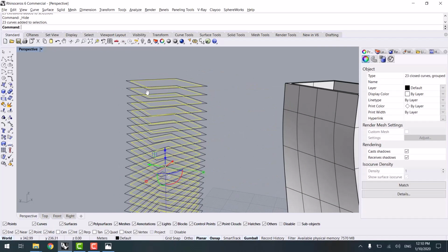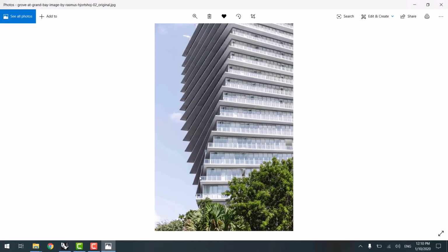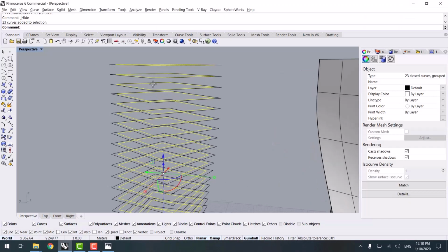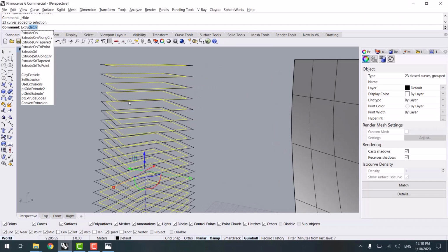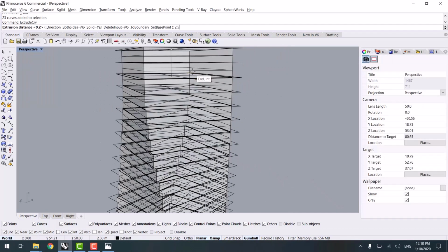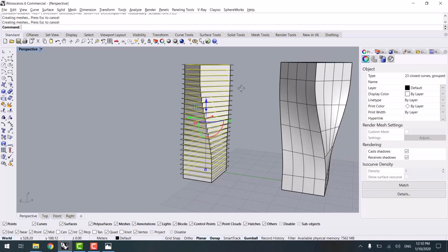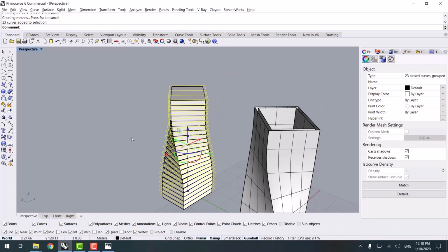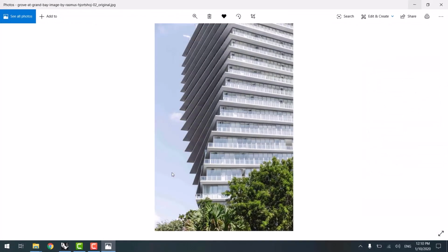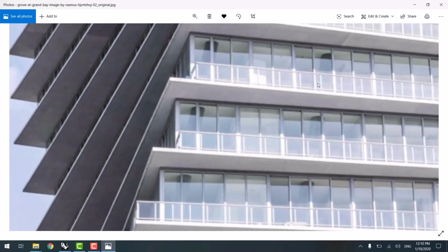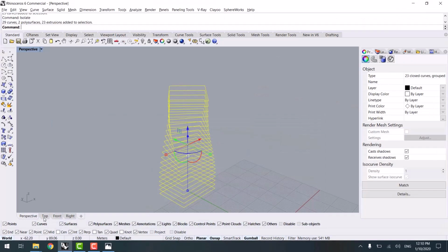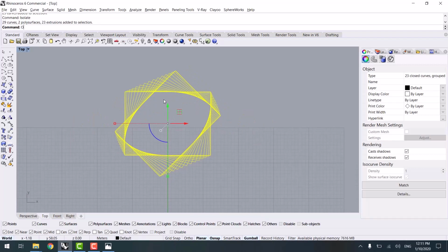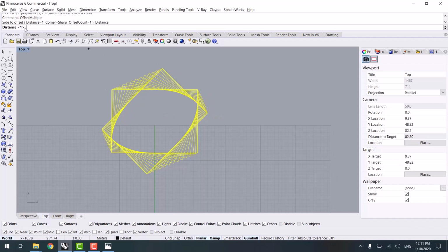And then we give a thickness just the same size as these floors. And I apply extrude curves here, as the 2.5 meters that we contoured. And then we select these curves, and then I activate the isolate command. The thing that I wanted to make is these bars that are here, and I switch to the top view, and I activate the offset multiple command. I wanted to have an offset from all these lines of 25 centimeters or 30 centimeters.